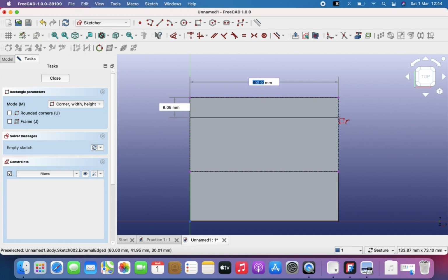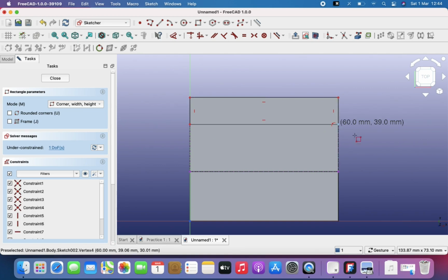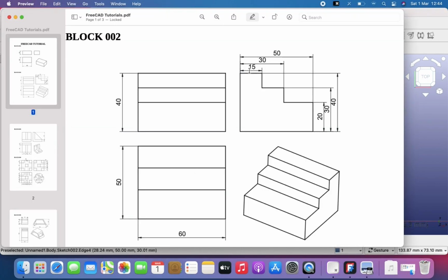Those are the things that are attached to my cursor. But if I bring it close to the center here, it is telling me that it is going to constrain it to the center, like to a point that is symmetrical between these 2 points here. So that is that symbol that is showing up that looks like 2 brackets, but I don't want that, or do I? I think I do actually, but I'm not going to use it so that I can dimension it. So I'm going to click here, and then the length is 15 millimeters.